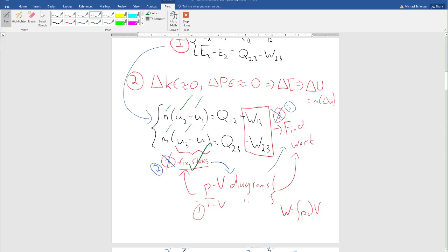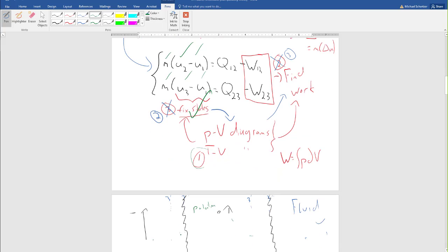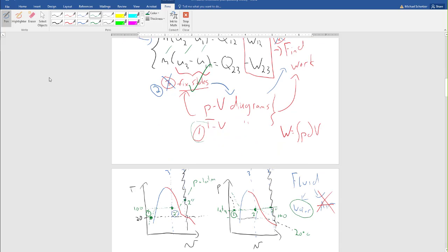So this is good. Now we fixed our states, right? We don't have this information yet, though. So let's finish our TV and PV diagrams. We know our state 3, because it was a superheated vapor, because basically V3 was on that superheated vapor table.